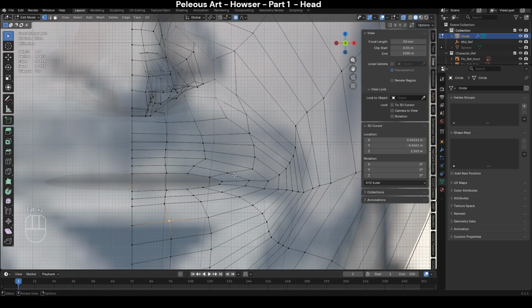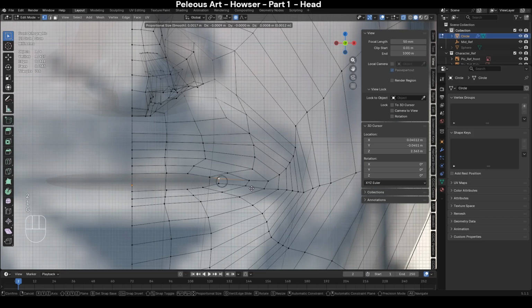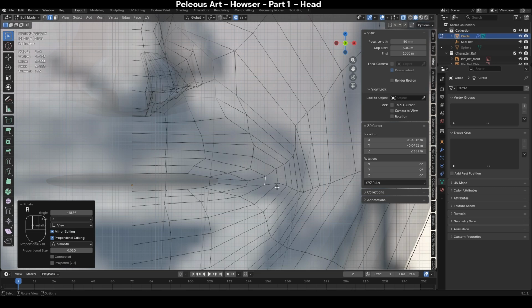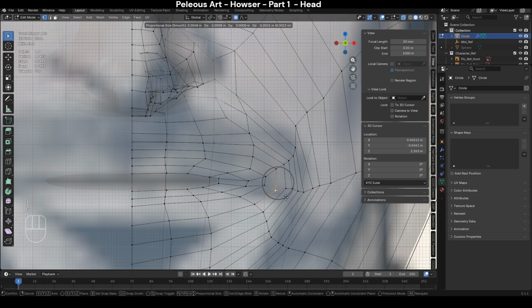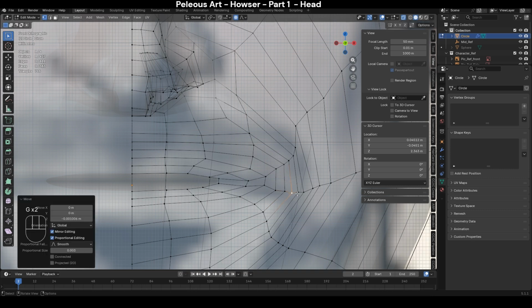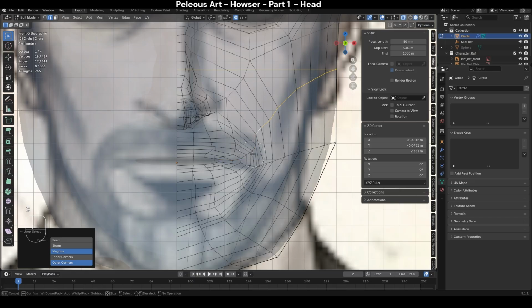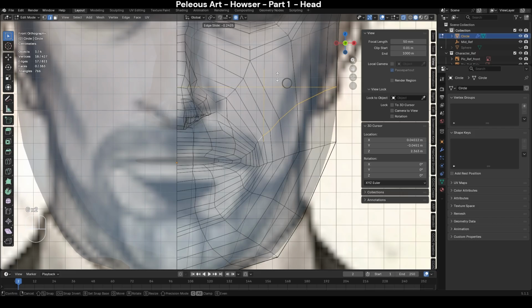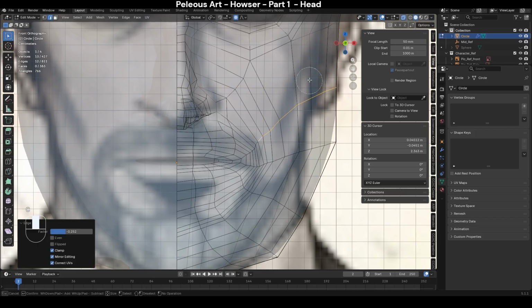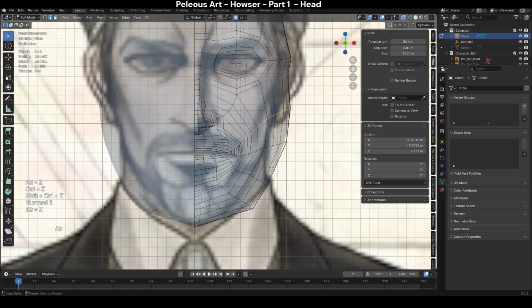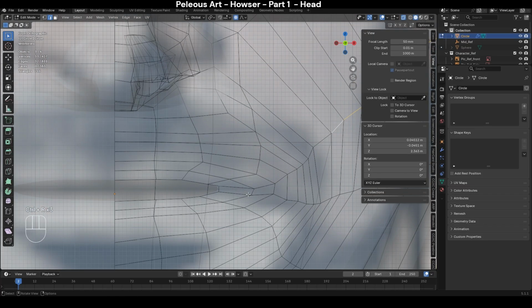All right, but we need a bit more topology to work with, so let's align this a little bit more, and then we'll add some. Just move it according to the reference, guys. You see the picture, what's going on behind. Just meeting up the vertices. Okay, select all of that with Alt, and then G G to move it down. Okay, you can delete with the middle mouse button. Maybe we'll add here a loop later. Right now it doesn't seem necessary.